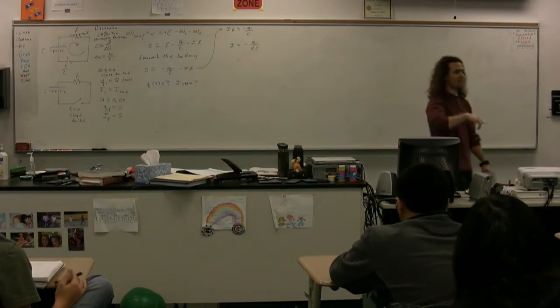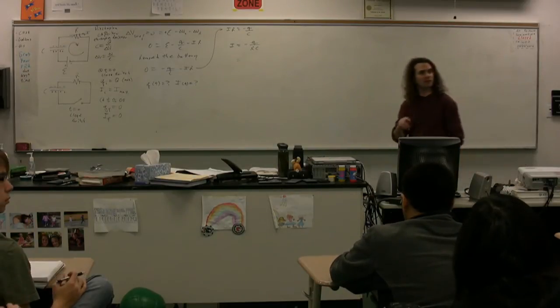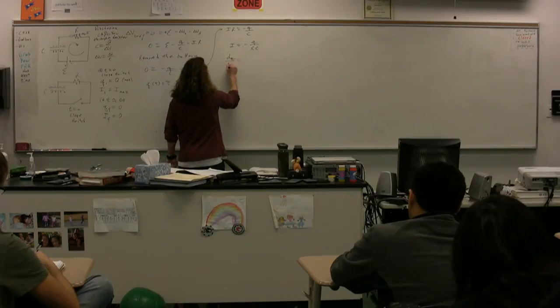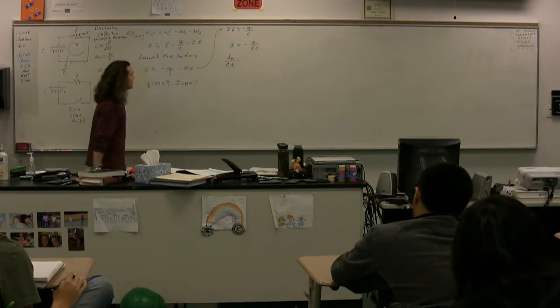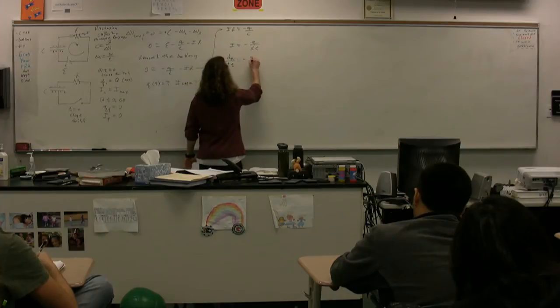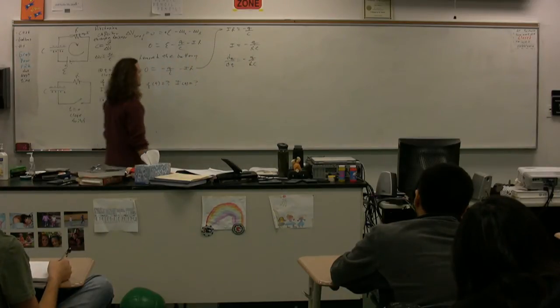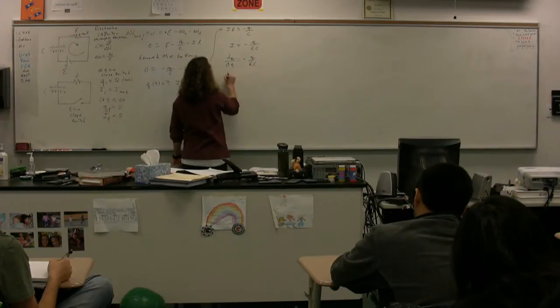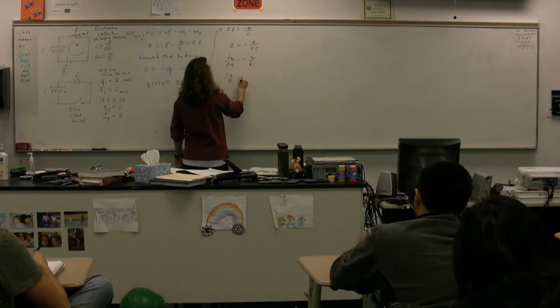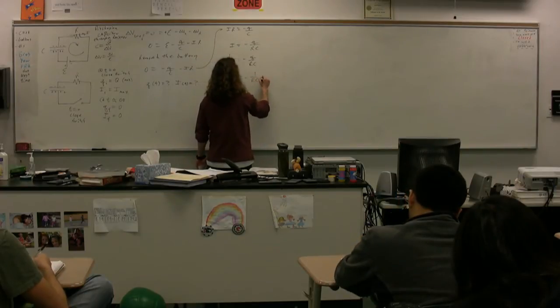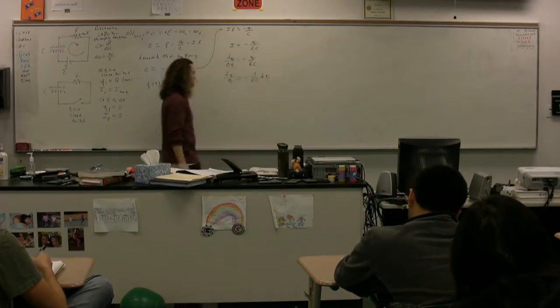I'm looking for more the definition of current. dq over dt, by definition, is the derivative of the charge as a function of time. So dq over dt is equal to negative q over RC. Let's bring charge over to the other side and bring dt over to the other side. So we get dq over q is equal to negative 1 over RC times dt.